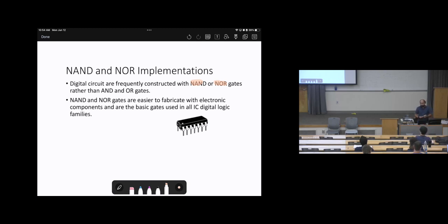Then we need to make sure to build up the problem. When should I run this device? I convert this to a written problem. After that, I can assign variables. The reading of, for example, the temperature sensor is variable A, of the humidity is variable B, of the light is variable C. Then the function F is the fan. So I need the fan to be on and off depending on the sensor measurements.